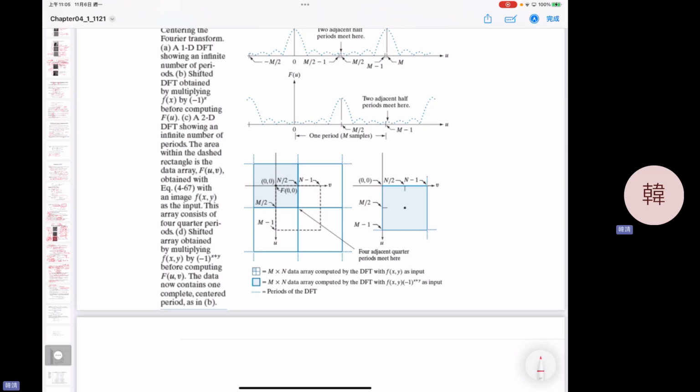The high frequency component stays the same because there's no edge. Because the periodicity tells me there's no edge there. So unfortunately, your low pass filtering doesn't cause any effect on this boundary. However, if you pad 0 before repeating the periodic signal, the edge occurs here, right? That's the reason. Because you pad 0, pad 0, pad 0, pad 0. So there is indeed an edge in the original one, and the result will be like this.